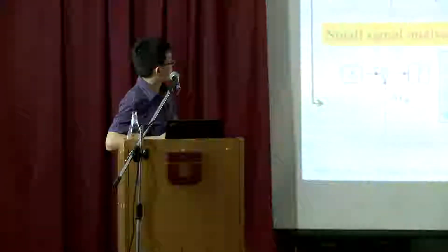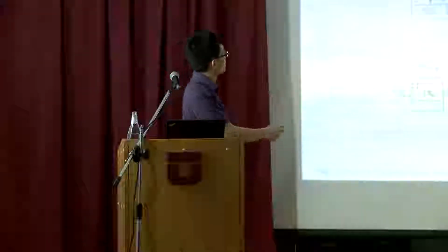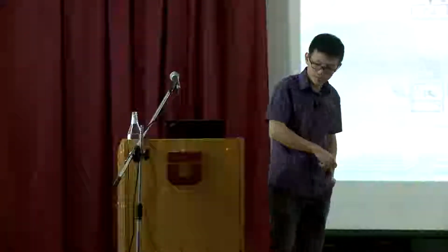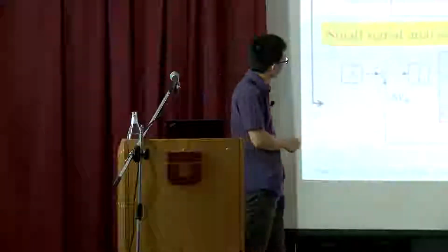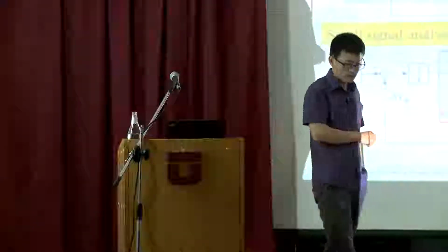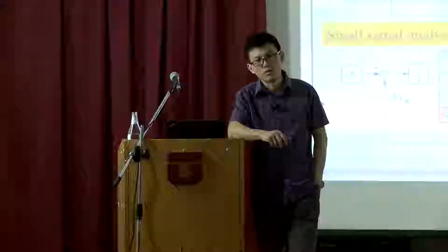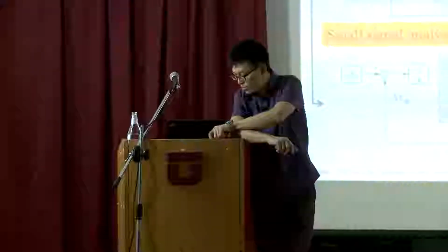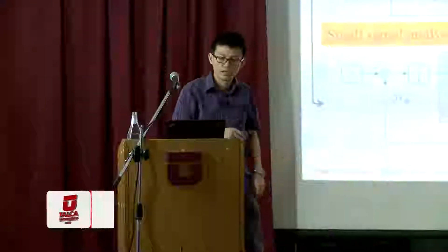One thing to start with is, of course, you have this complicated control structure. What I'm going to end up with is a single line architecture. What's really happening is, firstly, the current loop. When you design the current loop for electric drives, you always have very fast dynamics in the current loop.